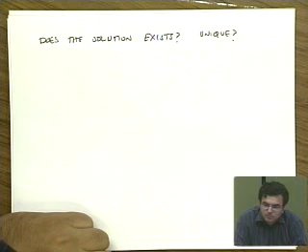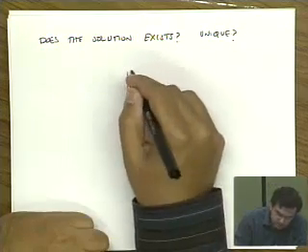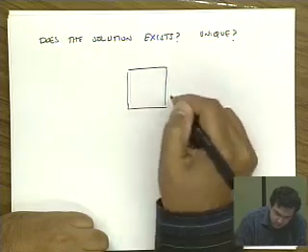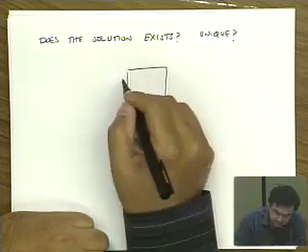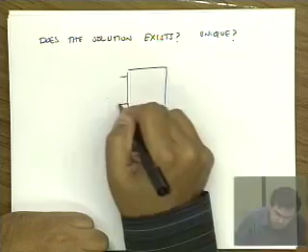Well, I think it's not necessary that a solution exists. For example, if the input resistance is at the same time the output resistance of the two-port, then we're not necessarily able to match it exactly without any further matching network. Okay, so let's say we have this two-port, and we found out that we have to provide a biconjugate match, right?